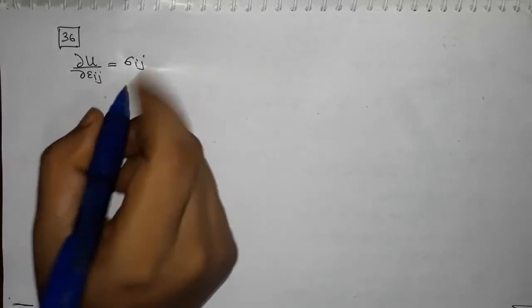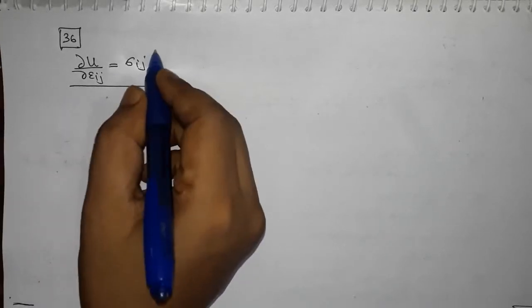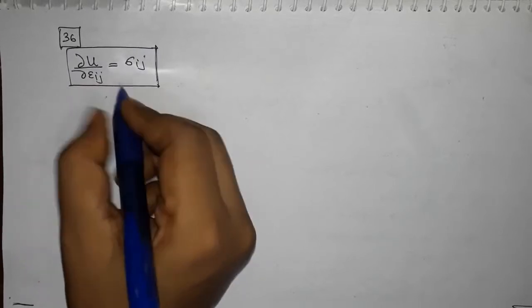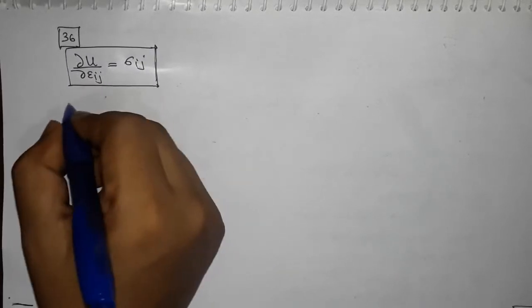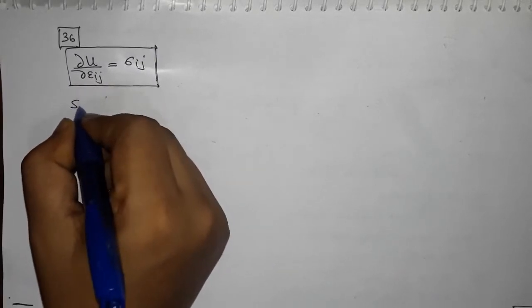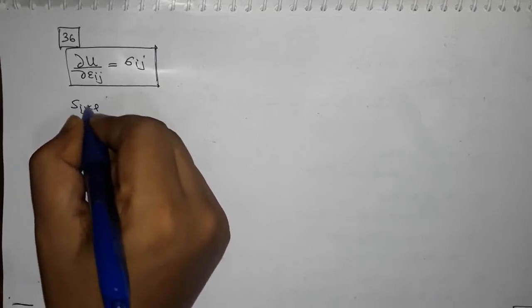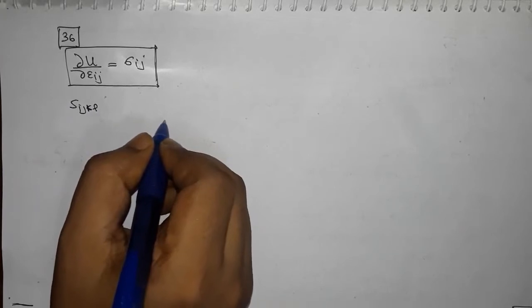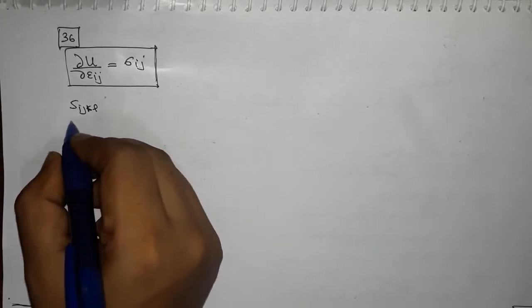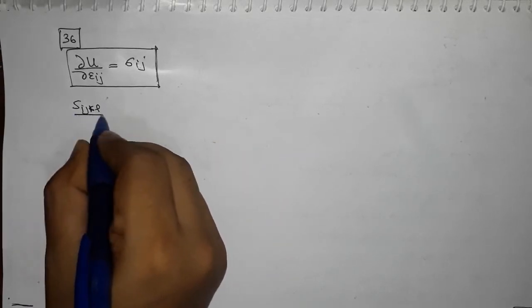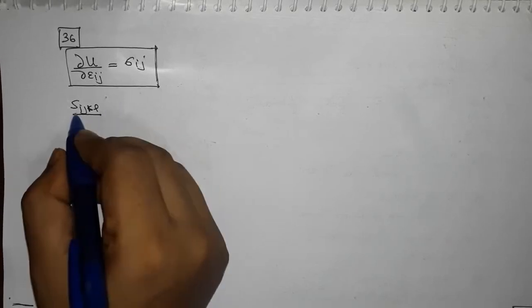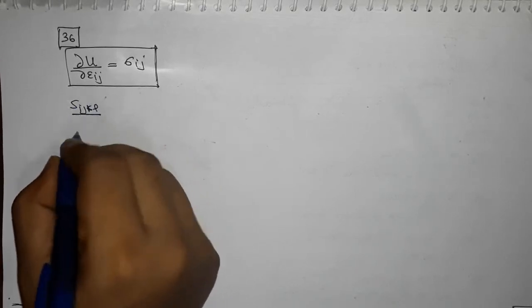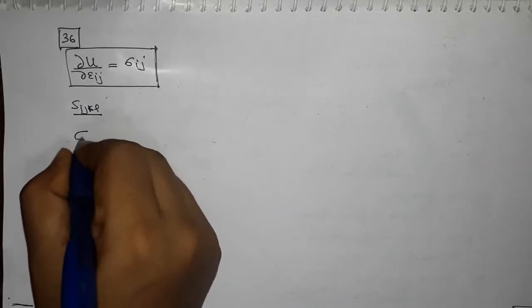So now, before utilizing this, we have to have a contraction of notation. So instead of writing Sijkl, now we can apply a contraction. What we say now is that instead of writing 4, we write only 2 indices for this component. So let me open it up for sigma 11.